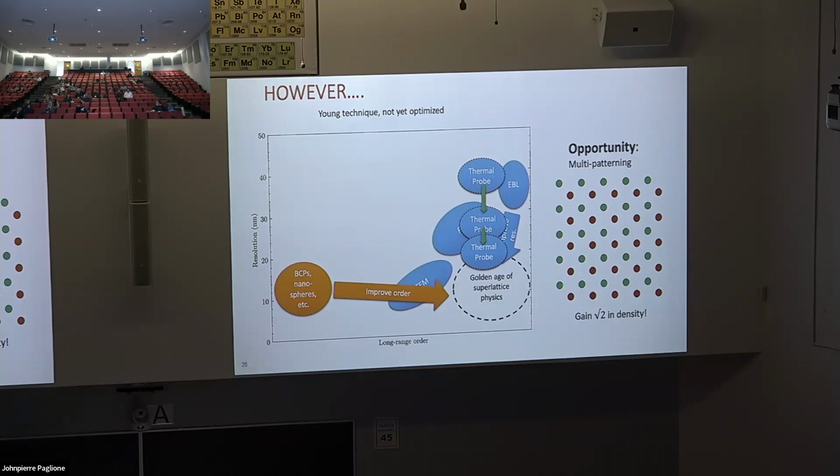How fast is the patterning compared to EUV? So this is very fast. You can pattern a fairly dense 20 by 20 micron area in a few minutes. It's more or less as fast as doing an AFM scan normally is. So you can go slower if you want, maybe a bit more resolution, but it's on the order of AFM time. And it's done in ambient, and it's all very easy. Just plug in your sample, ready to go.